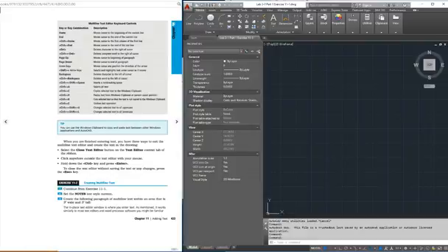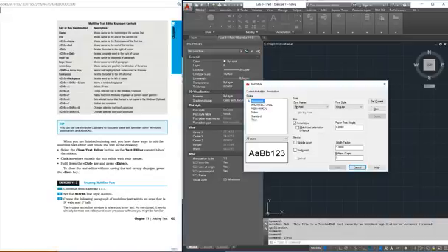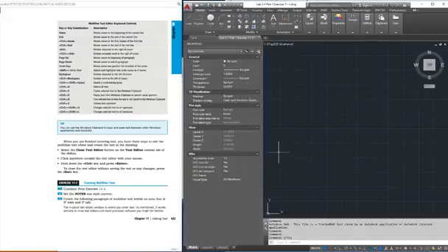It starts over here, page 423, the bottom of the page, and it says use the notes style as the current style. So that's pretty easy. I'm just going to go into my AutoCAD here, type style, open it up, select notes. You can either double click it or set the current button here and hit set. Say close. That's all you got to do.